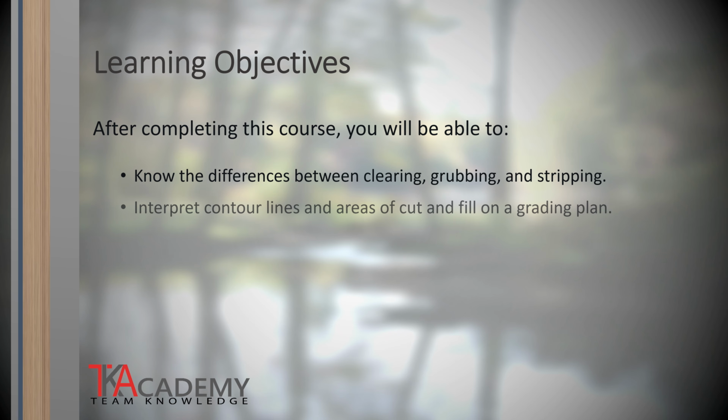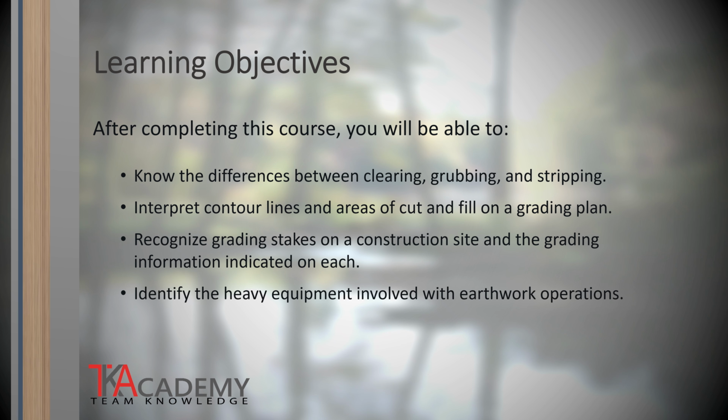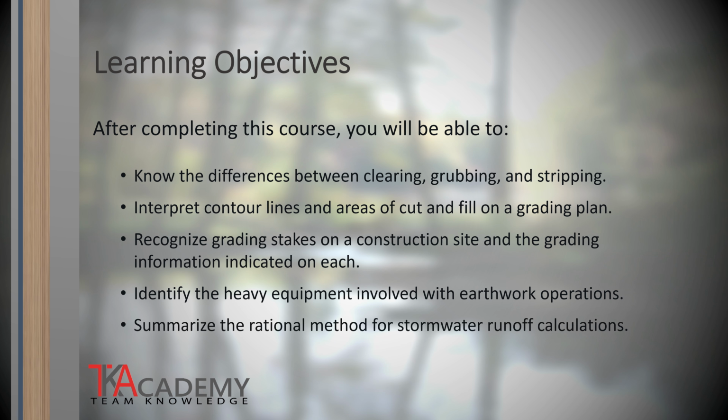In this course, we'll explain the differences between clearing, grubbing, and stripping. You'll learn how to interpret contour lines and how to determine areas of cut and fill on a grading plan. We will show you how to recognize grading stakes on a construction site and what grading information is indicated on each. We are going to identify the heavy equipment involved with earthwork operations. Finally, we'll summarize the approach toward drainage design and explain how to use the rational method for stormwater runoff calculations.